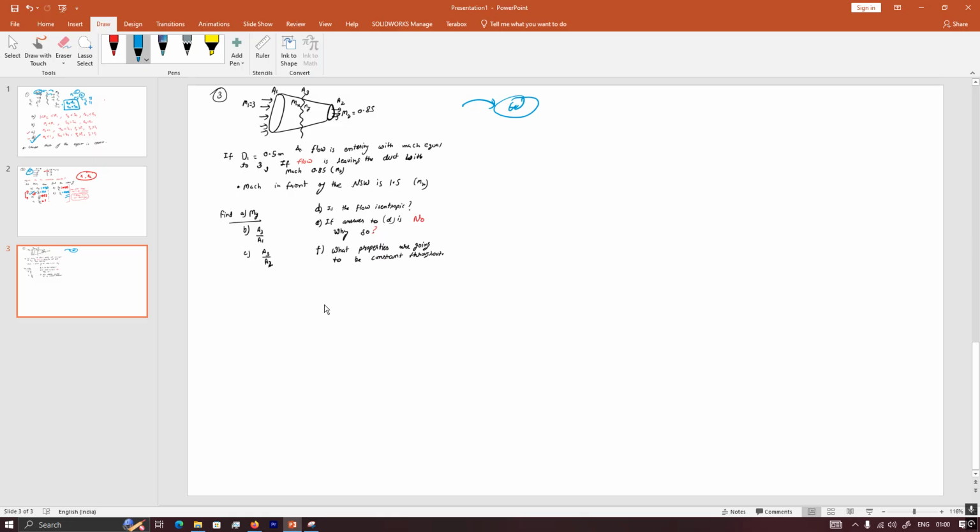Just think of it and tell me, is it a nozzle or did I say something wrong? Okay, so I'll correct myself. It is not a nozzle because your entry flow Mach is greater than 1, so it will see it as a diffuser. So your Mach entering should be decreasing till some point. So that's a diffuser for it.